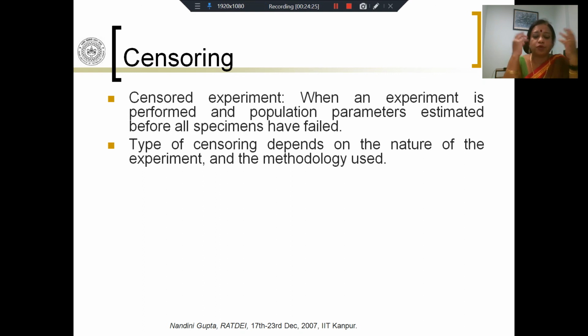And most of the time, when we take out the material which has failed, we see that the puncture mark is not at the center, where the rod is. If the rod is sitting on this insulating material, the puncture mark is not where the rod was, but at the edge of the rod.